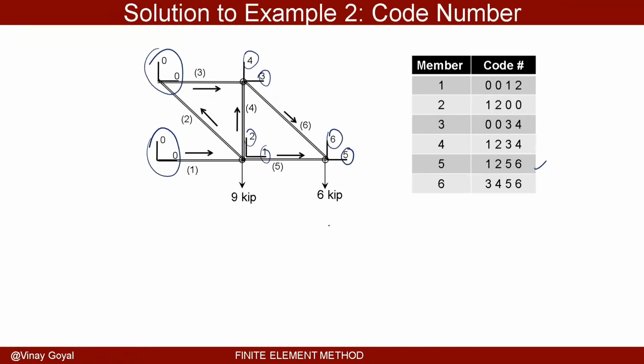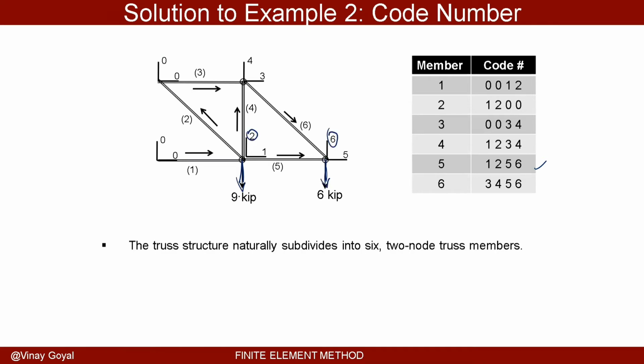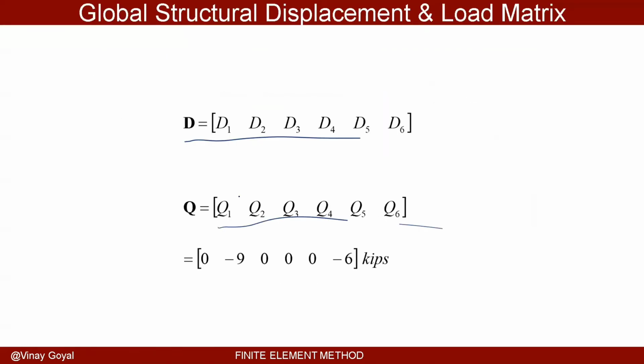Here I have drawn the degrees of freedom. So let me erase this so it's more clear. I'm only applying a load in this degree of freedom, and I only load in this degree of freedom, but in the opposite direction as they were defined. So that should be negative when I put it there. Therefore, the only ones that have values are this one, -9, and -6 for this one. Everything else is 0. I don't have any loads applied for anything else, just for those.